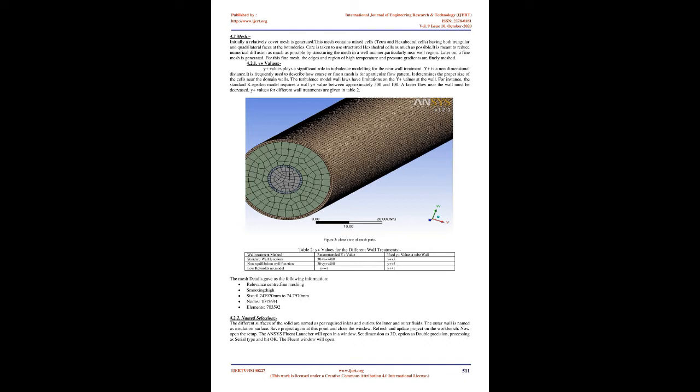Zhang et al. studied heat transfer enhancement for the shell side of a double pipe heat exchanger with helical fins and pin fins. The three-dimensional velocity components for the shell side with and without the pin fins were measured experimentally using the laser Doppler anemometer, LDA, under a cylindrical coordinate system, along with the fluid flow characteristics. The results show that for the shell side with only helical fins at large pitch, there was a pair of vortices near the upper and lower edge of the rectangular cross-section. The weakest secondary flow occurred at the center. By installing pin fins, the three-dimensional velocity components in the helical channel were strongly changed.